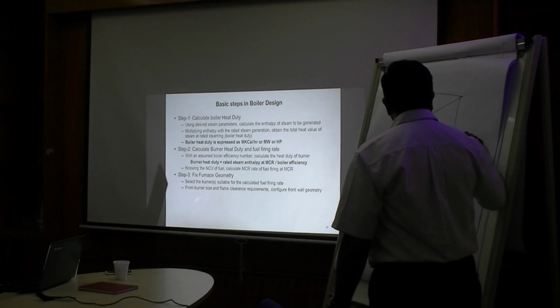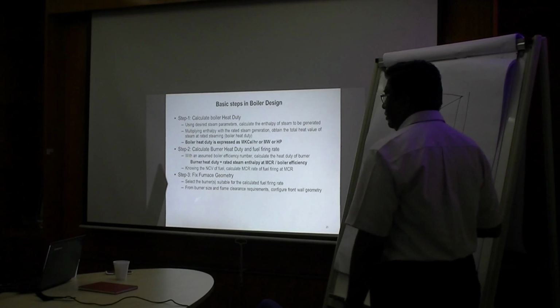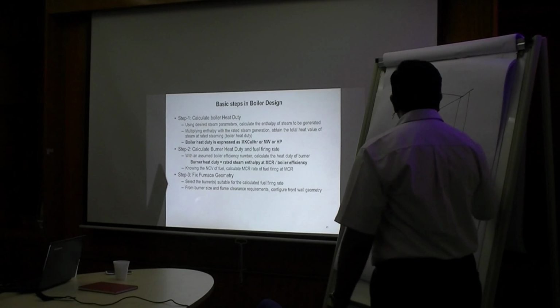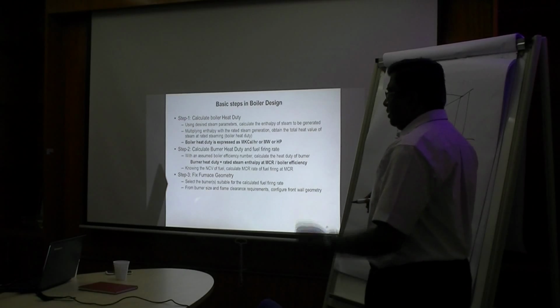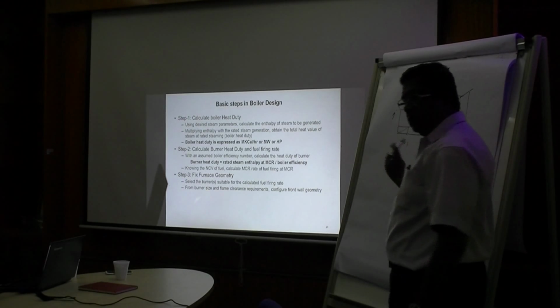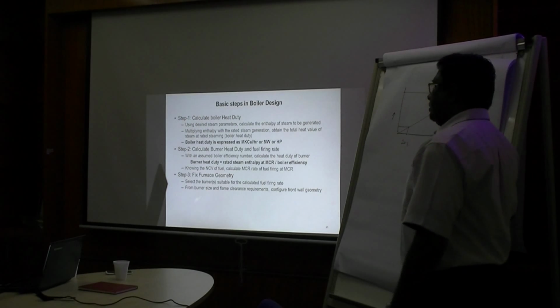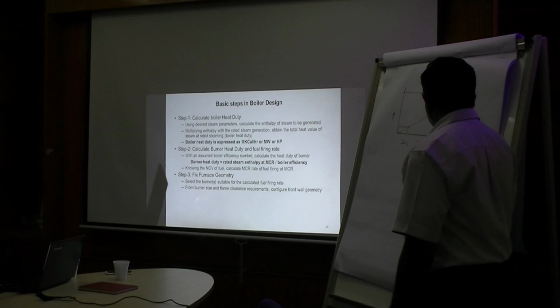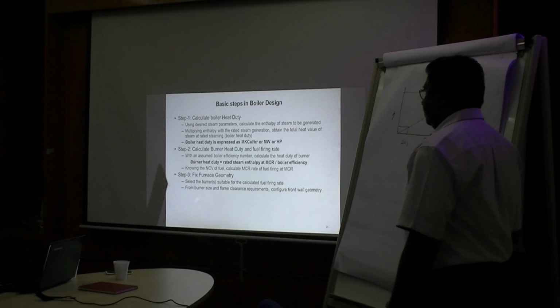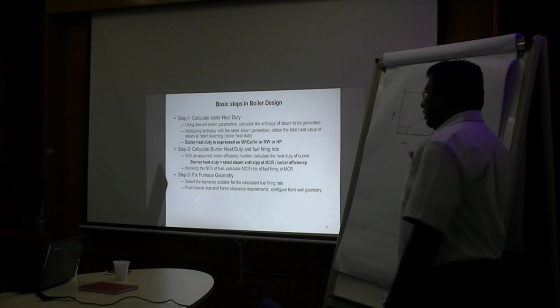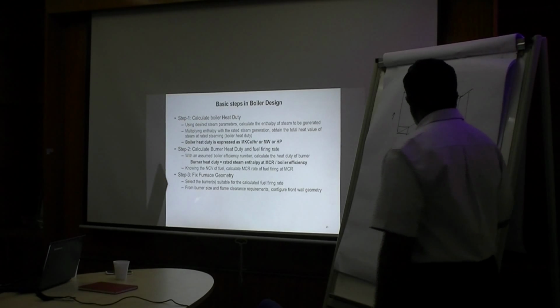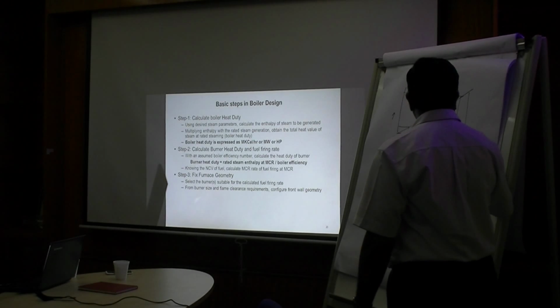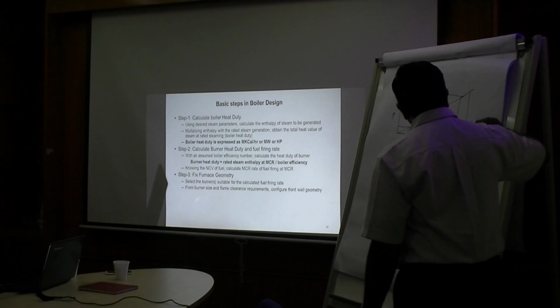Then you also have to have peak load 10%, and then you have to have a standard margin of 5% over the peak load. So 110 plus 5% of 110. This is 100, this is 110. So 110 plus 5% of it, which is 5.5, so 115.5 equivalent. So your burner design point is here.